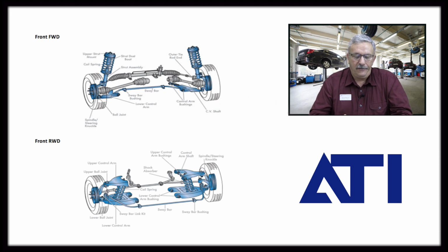The difference being we've got a big, heavy steering box that goes on the rear-wheel drive type vehicle. And this is traditionally what you see on trucks, even light trucks. It's a smaller box, but it's still a significant weight, versus the rack and pinion system, which is lightweight. It's basically an aluminum tube with a steel rod that runs through it, and it's a worm gear that operates it. So that is the difference between the two.